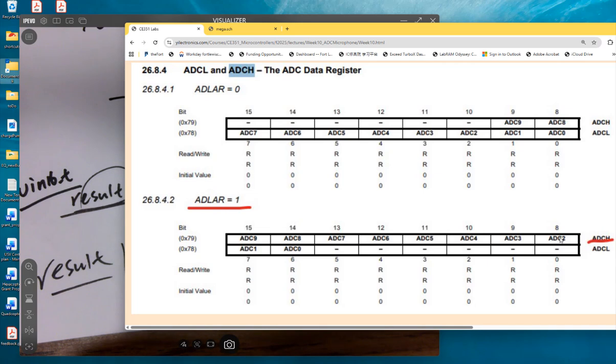So if we directly use these binary bits, we're pretending this one is a 1, not a 4. So it makes sense that we probably should shift it to the left by 2 bits. I think that's the case, but let me confirm with the datasheet after this, okay? So if you don't shift it, you're actually dividing your result by 4.